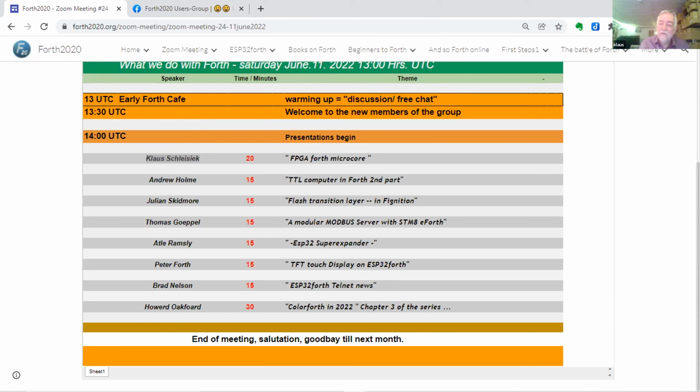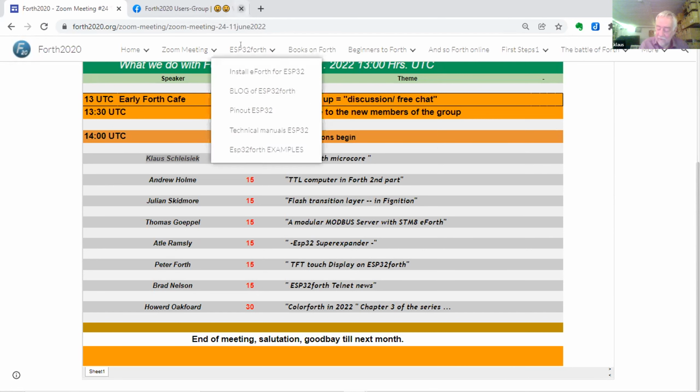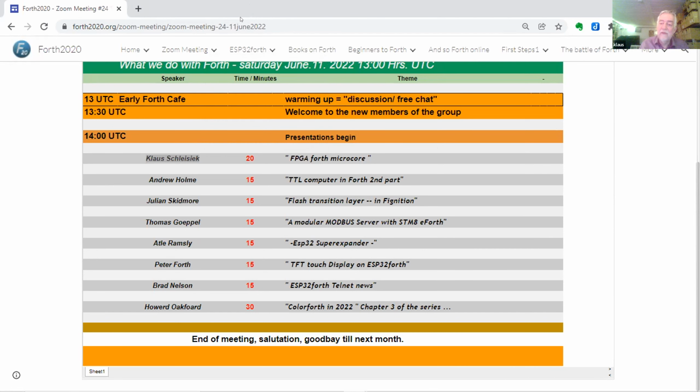You specify how wide your word width is, and then you specify how wide the word width of your external memory is, and then all the rest goes automatically via this VHDL entity, because you may have to do several accesses to get the full data word width from external memory. That is also already part of it. Excellent, thanks.